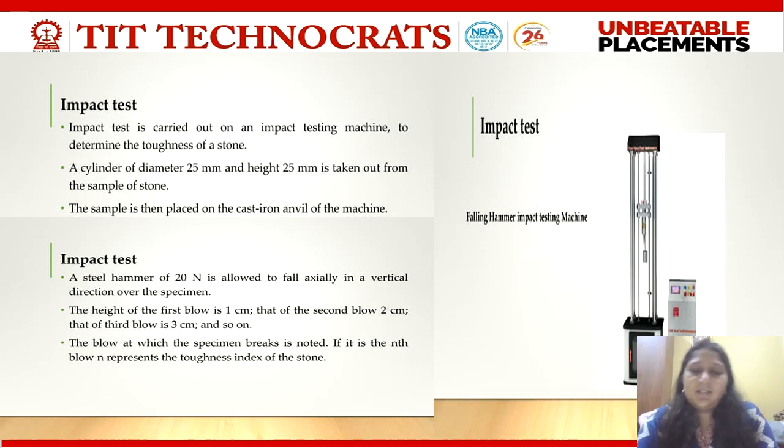For this particular test, I take the stone aggregate sample. I place it in 3 equal layers in a cylindrical mold. After each layer, I tamp it with a tamping rod so that all the air voids are removed. Then the second layer, then the third layer. After each filling layer, I tamp the material so that maximum material gets compacted in my mold.